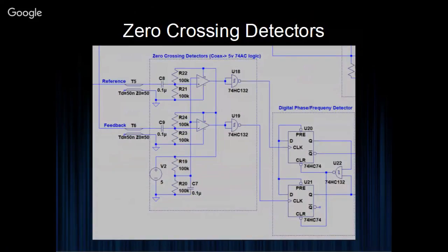Okay, so in this case, when you would be reading those as a transmission line, it would affect the reflection stuff in the transmission lines anyway, right? Even if you properly terminate your... Yes. However, you've got to look at the load impedance of the scope, and typically the scope is sort of like 1 megohm. So you'd probably get more of an impedance mismatch from the T-piece than you would the scope itself.